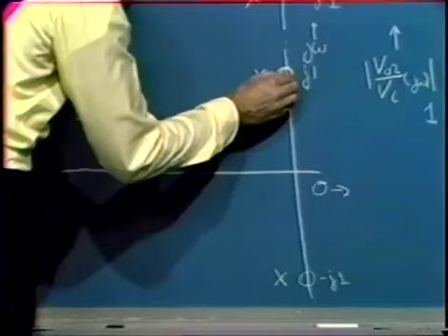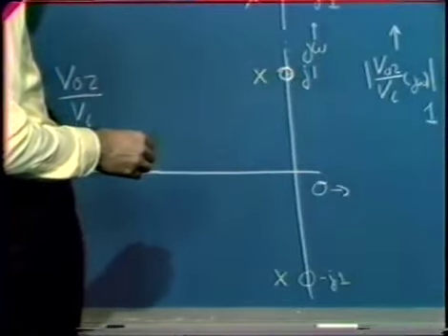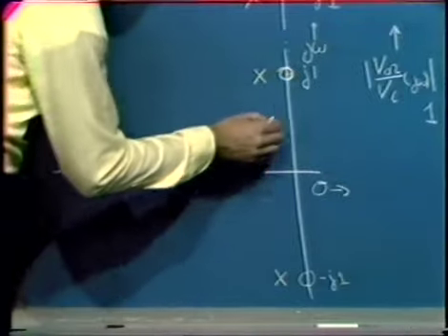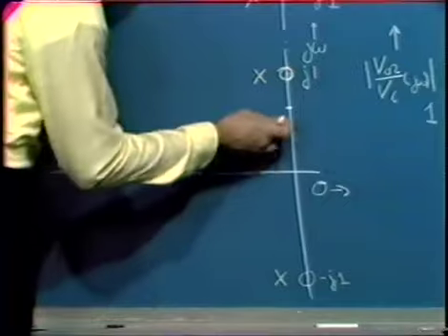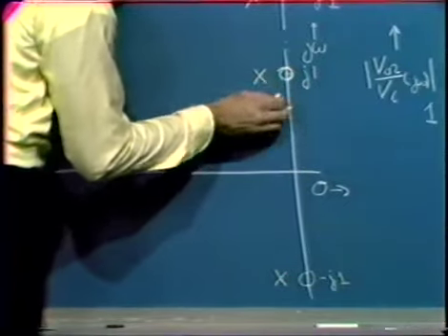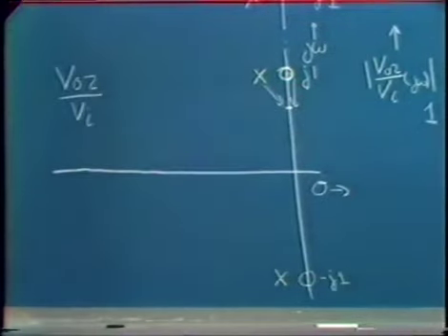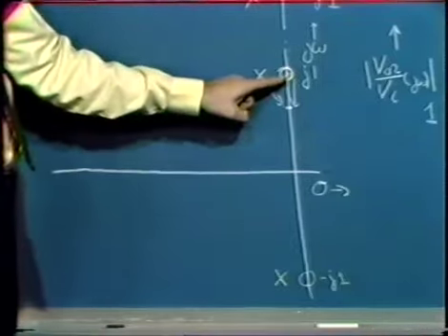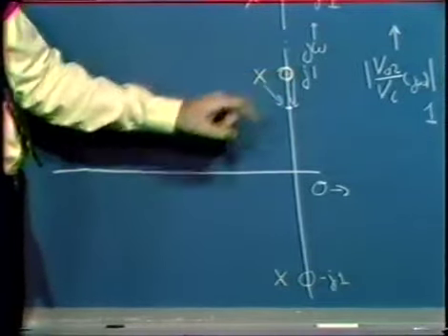When we look at the frequency right here and ask for the frequency response, it must go to 0. However, if we're even slightly displaced from that point, these two vectors just about cancel, these two vectors just about cancel. And so the gain of this network is the same at almost all frequencies except in the immediate vicinity of the 0. And of course, at the 0, the response must go to 0.